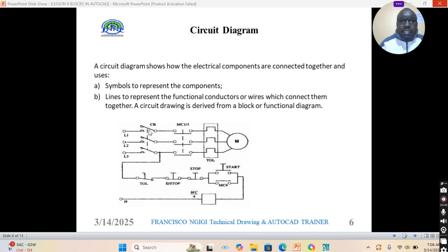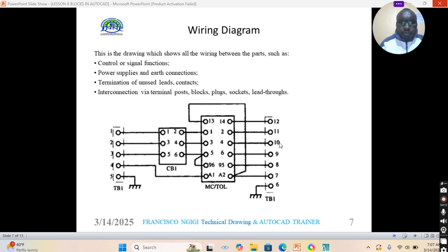And you can see this one inclined, so here we are using polar. And here we have a triangle, constructed using the ortho command. They have been labeled CV, and here they have used the dtext command.